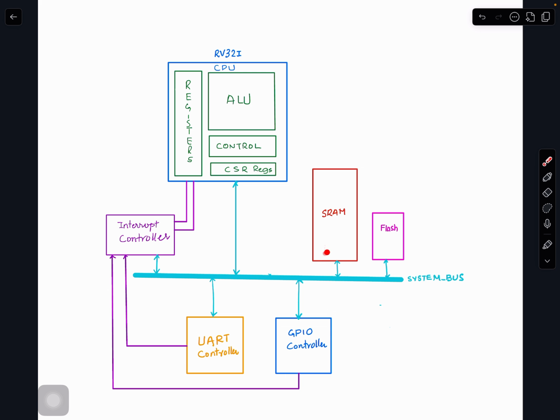We always refer to an SRAM, an external memory. Remember how much the address bus is? The address bus was 32-bit, right? We were saying 32-bit. So that means we can access 4 gig of data. But in our system, we need a flash. When the power is off, the flash data still stays there. So that's a cool thing. On our PCB, we can put